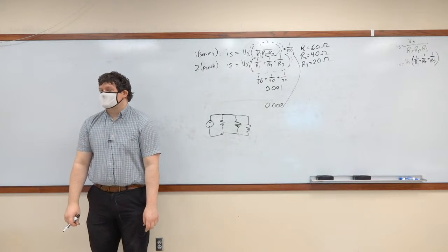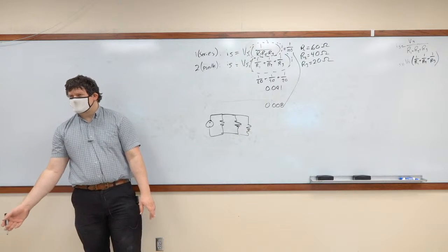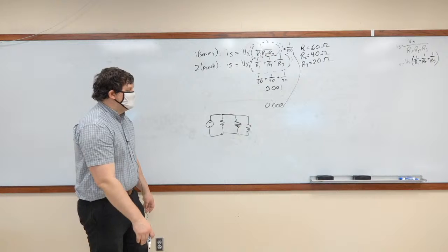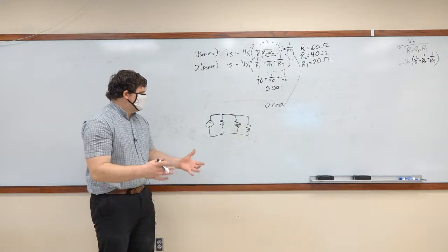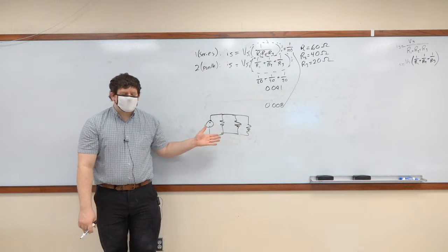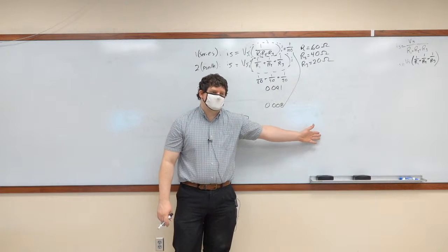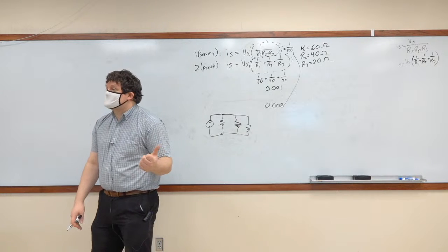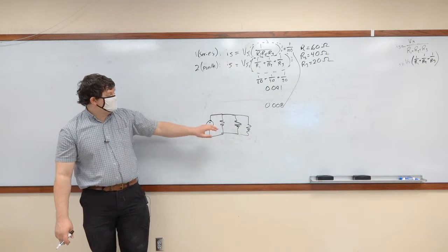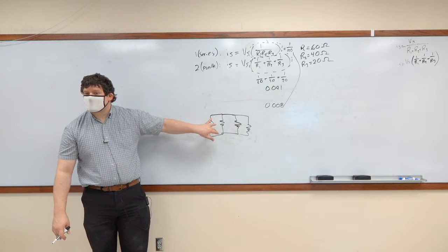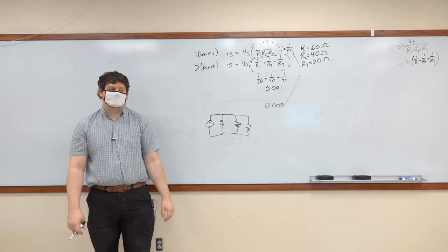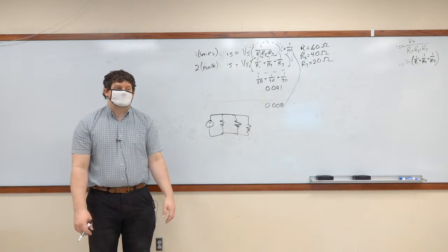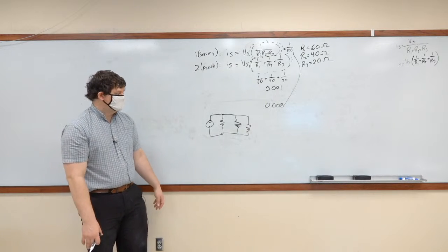So if I keep adding components to this voltage source, we will continue to see increased power consumption out of it. All of these lights are connected in parallel for that reason. LED lights are connected mostly in parallel. You usually have strips where they're connected in series, but it's for this reason. You can have an entire strip of lights, and the power consumption from the battery will change. You just add another light. But everyone is going to see the same amount of power going to every element. It doesn't change anything. Okay?